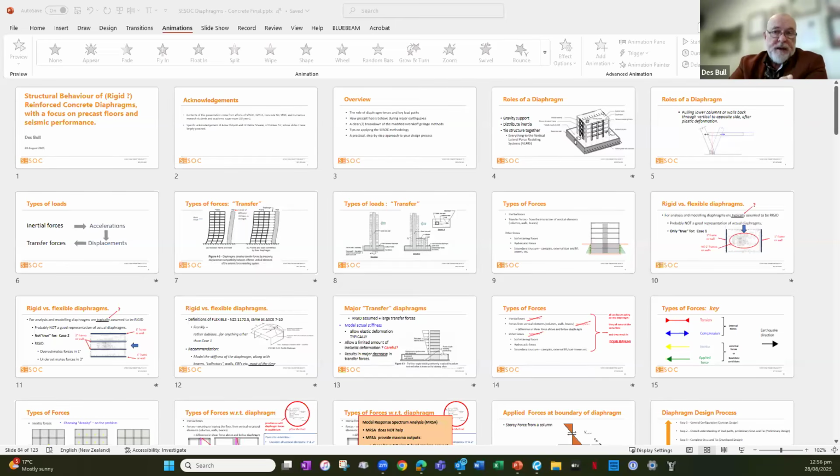A lot of the literature coming out now says we have done this to Chapter 17 and we will get up to the rupture strength of the bar, which is what 3101 requires. It's not yield. Don't do the check at yield. It's actually fsu we're looking for out of those bars. That's a 3101 requirement. The older guidance used to do all the hef, the embedded item depth, based on yield, so they're all too short. But a lot of the modern inserts and couplers have caught up with that. It's something to keep an eye on, that's all.